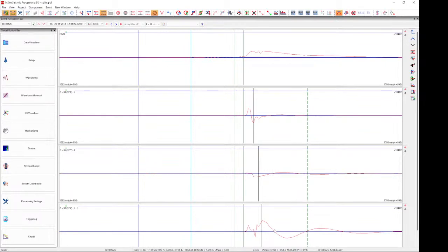If I make it more strict, or I increase the size of the window, it will smooth our signal further. So this is the way this Hampel filter works, and as I said, the main idea is removing outliers and removing high spikes in our traces.